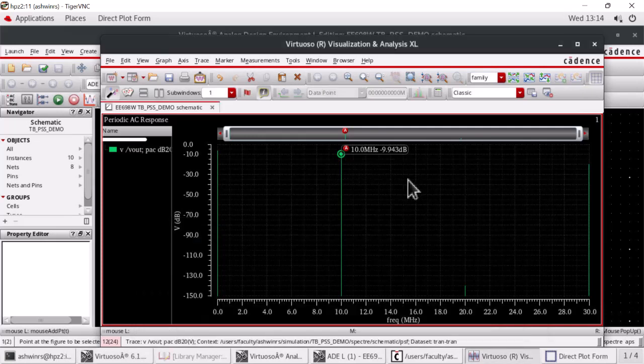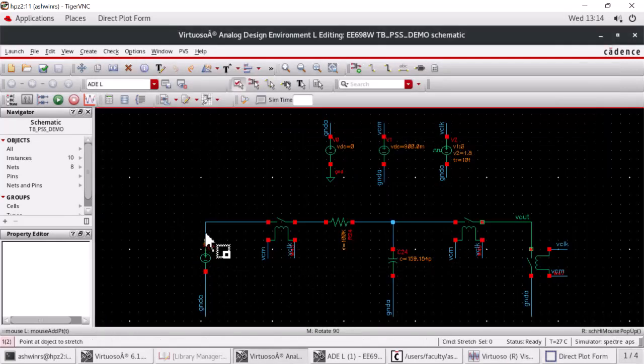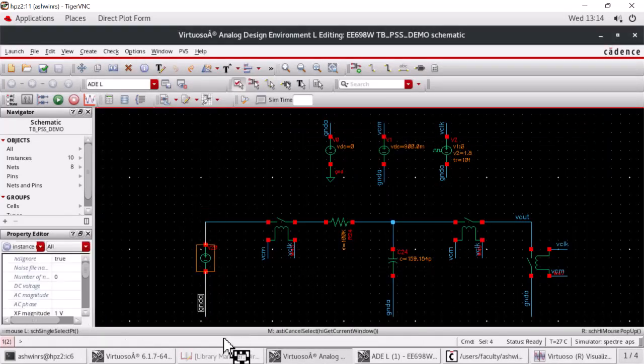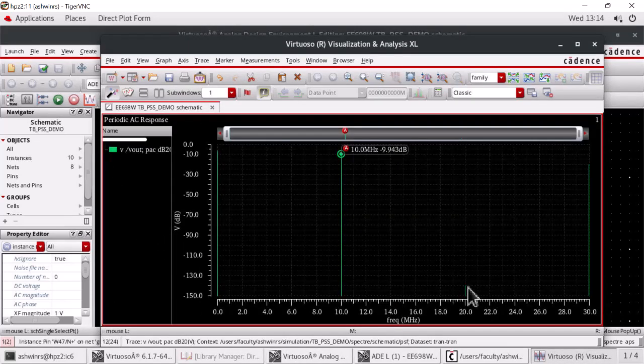Okay. And in the last class also we saw, when you apply a DC here, this will also be a DC. At the output, you'll have a periodic square wave with 50% duty cycle. So what can you say about H2 of j2π0? 0, right? There are no even harmonics. And that's exactly why you have minus 140 dB, which is close to 0 for all practical purposes, right? It's 0, and again you have a tone at 3 Fs.